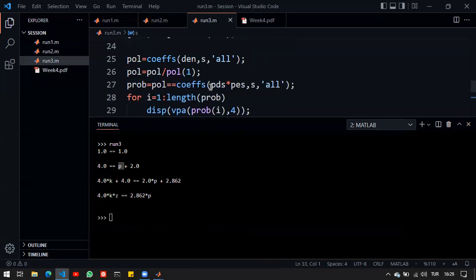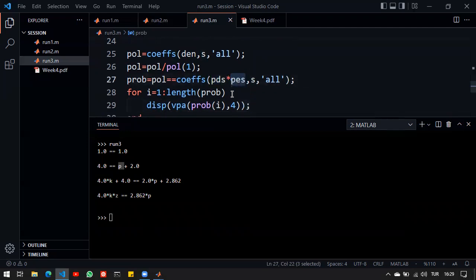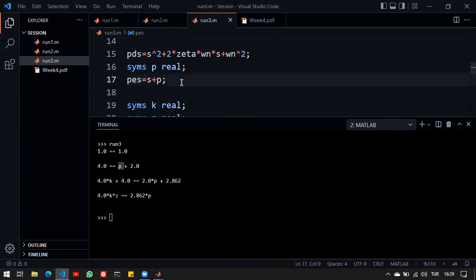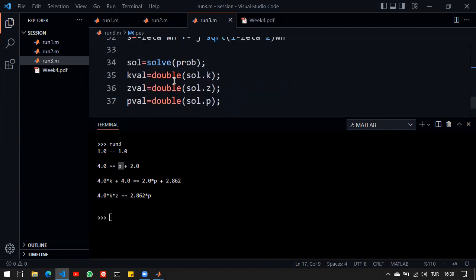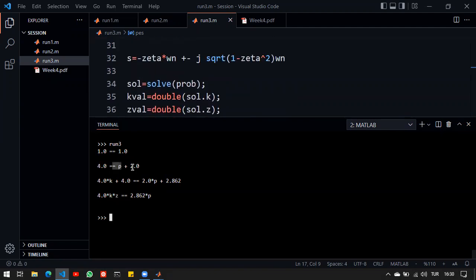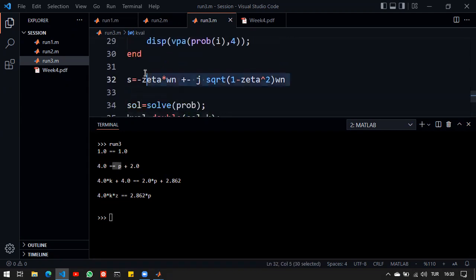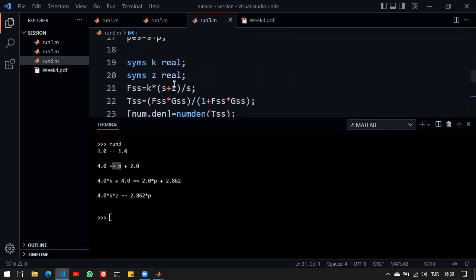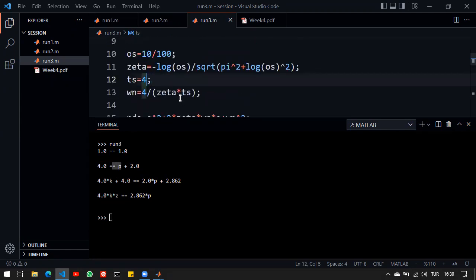Now, since I'm multiplying this desired or dominant pole pair with a residue polynomial, I need to have also a stable one. So the definition of it is quite straightforward. It is s plus P. For strictly positive, real P values, I'll end up in the left half plane again. So therefore, I should check for P. Now, it could be the case that P is negative, which would mean that the closed loop is unstable. And that's basically determined by the settling time choice here. So it seems like choosing 4 is good.